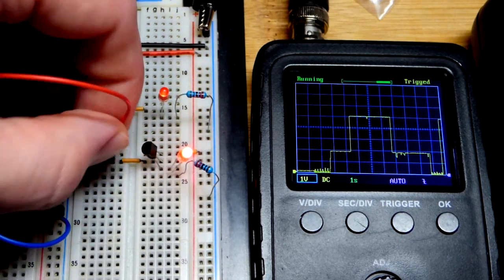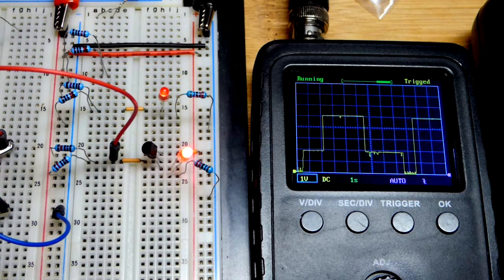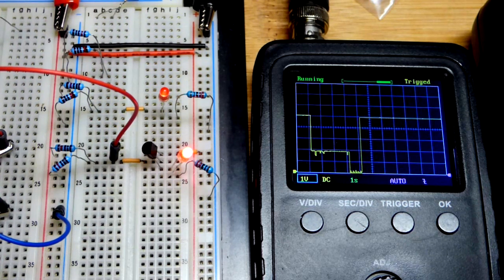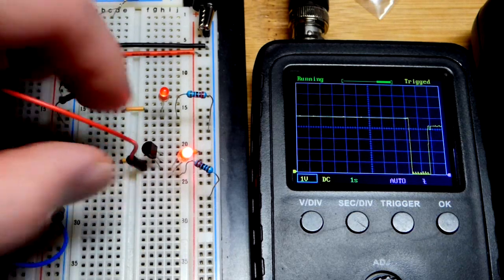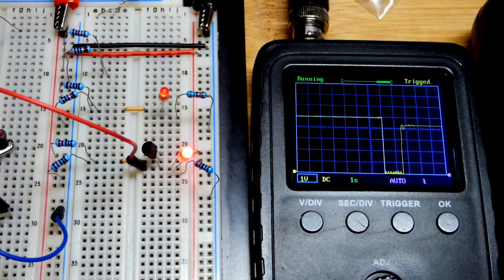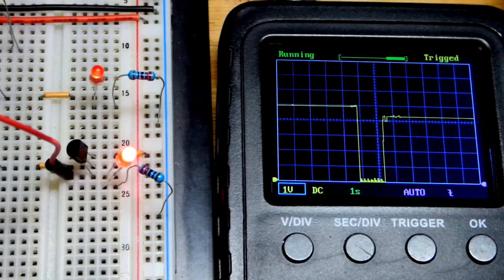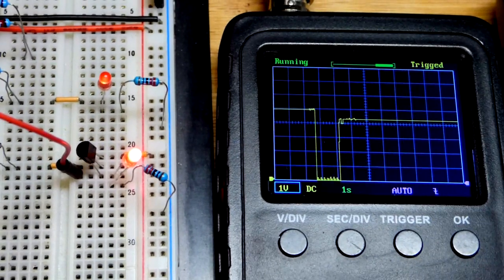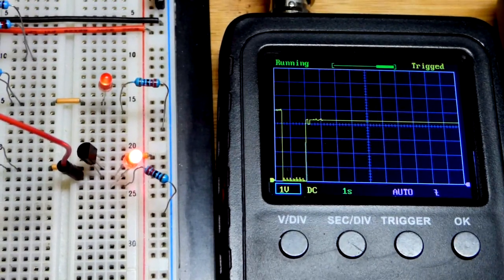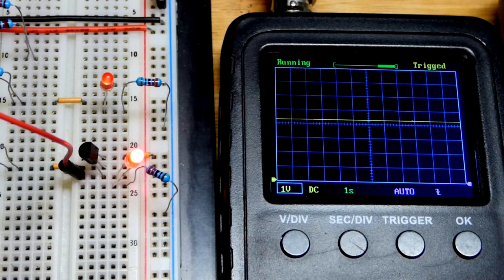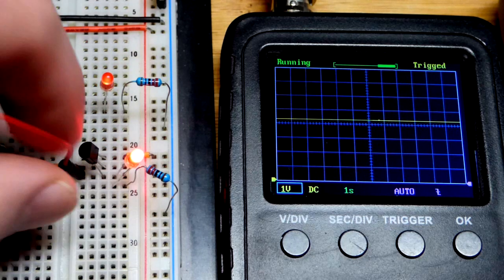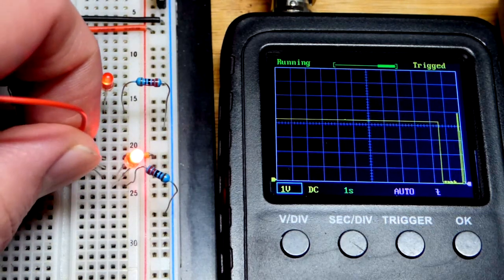Now we come over to the transistor circuit, and there you can see we got 5 volts as far as the voltage divider is concerned. So it's holding its 5 volts. Now we come to the emitter of the transistor, and there you can see, looks like maybe we're losing closer to about 0.7 volts, it looks like. But it's pretty close to about 0.6 volts that we are losing from the 5 volts that we are given as a signal there.